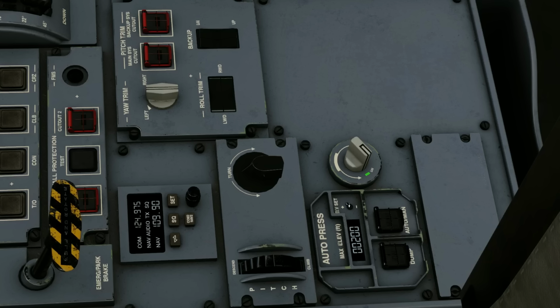We can use this to set our landing field elevation. So set your destination elevation so that the pressurization system follows a special scheme and knows what it's aiming for on descent. If you want to be in manual, good luck. No. You take it out of the detent, and now you have full control over your outflow valves. Essentially, 11 o'clock is considered closed, or no rate change, and then we're commanding rate changes with this knob, all the way from 2,500 feet per minute up down to 2,000 feet per minute down.